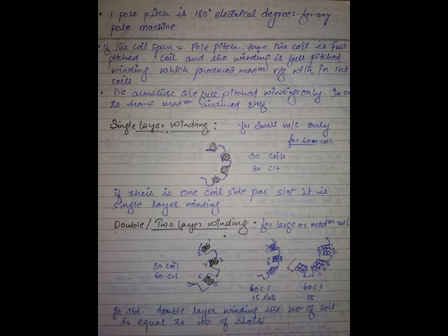If you connect them in parallel, say this is one conductor, this is one conductor, this is one conductor, this is one. Each conductor, due to cutting of flux, let us say 1 volt is induced. What is the total output voltage of this particular circuit? I am taking an equivalent circuit for the winding, just for understanding. 4 volts. Next, let us say each conductor's current carrying capacity.